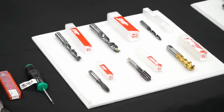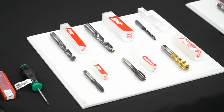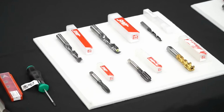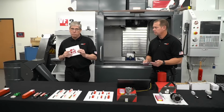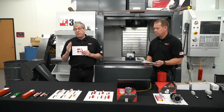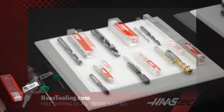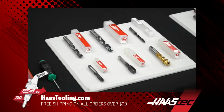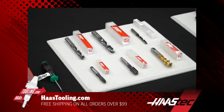So the 2 styles that we have, 2 geometries, one is for steel and cast iron. The other geometry is for stainless steel, high temperature alloys, and can actually be used on aluminum. Now the drill for stainless and high temp alloys is only available in through spindle coolant, because those applications really require coolant down in the cutting zone. The drills for steel and cast iron, you can get in non-TSC and TSC versions. They're a lot more resistant to heat in those materials, so you don't necessarily need to use through spindle coolant on those carbide drills for that material.